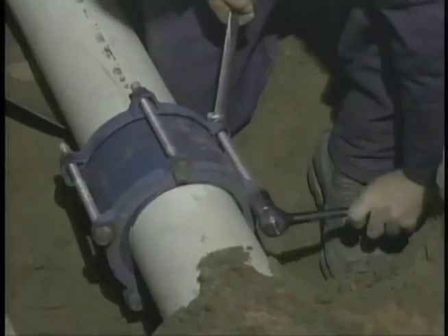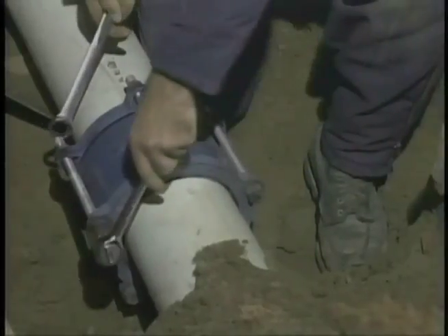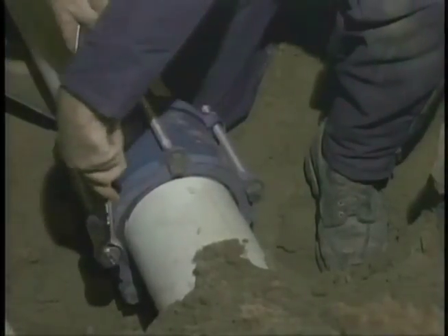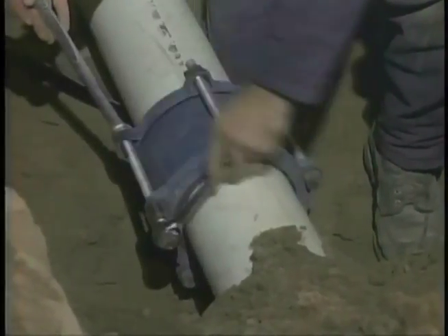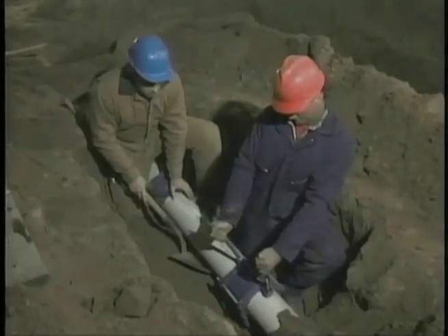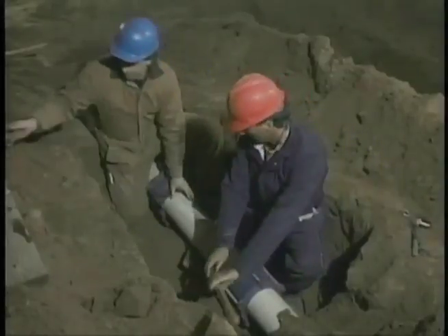Start with any bolt and tighten a couple of turns. Then, tighten the opposite bolt. Make sure the bolts draw the coupler in evenly and compress the gasket. After completing a few rounds, finish tightening to the final torque using the rotational sequence.